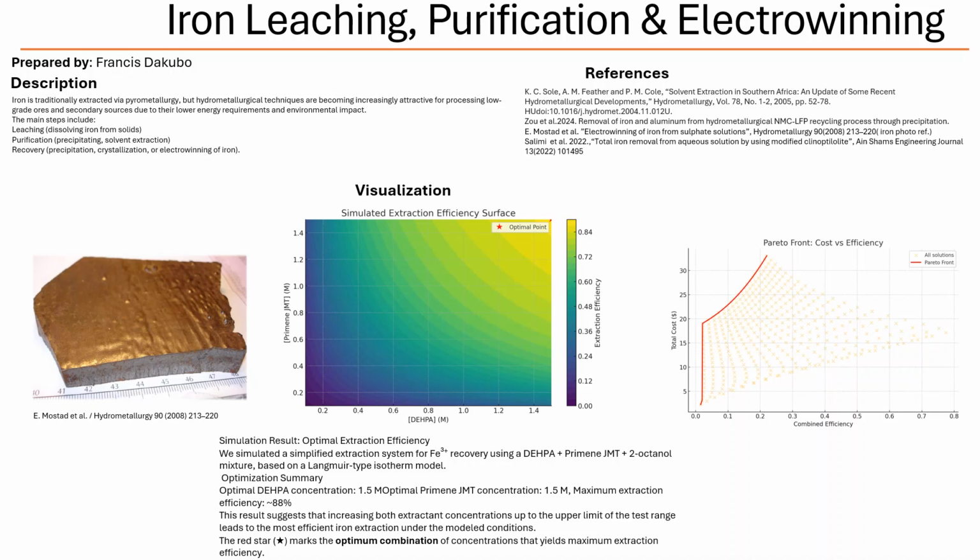And the pyro process achieved a pretty good current yield, right? Yeah, 85%, which is pretty impressive. Yep. And they did it with a power consumption of 4.25 kilowatt hours per kilogram of iron. Not bad. They also mentioned adding salts to the solution, like sodium or ammonium sulfate. Why was that? Two reasons.